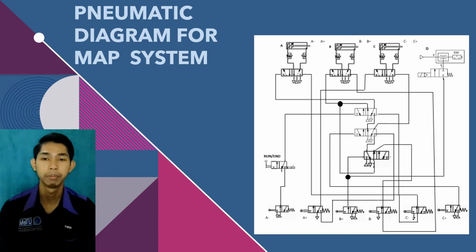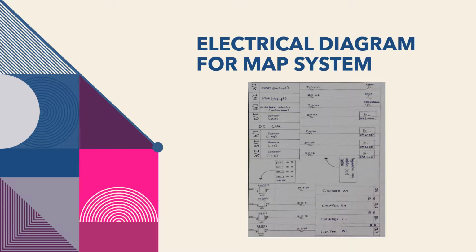Next step is cylinder B. Cylinder B will extend and retract for 2 seconds, and after that ejector D will extend and retract for 2 seconds. Last step: if using recascade, go to end, and if not, repeat at step 1.